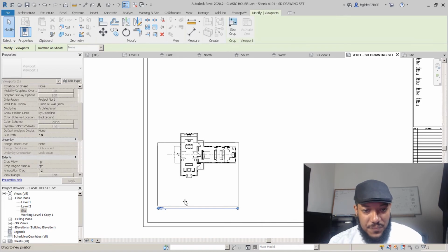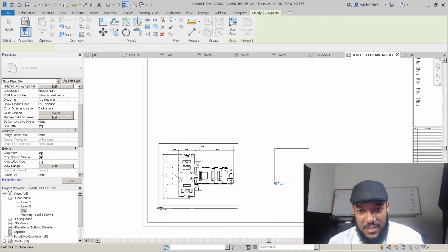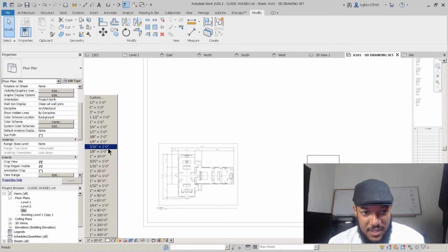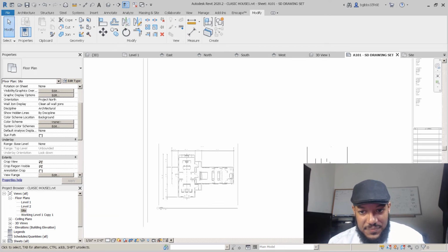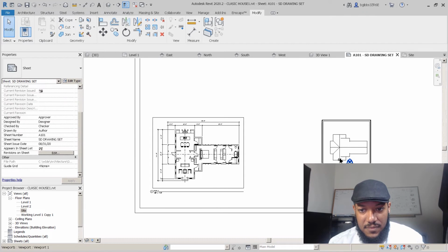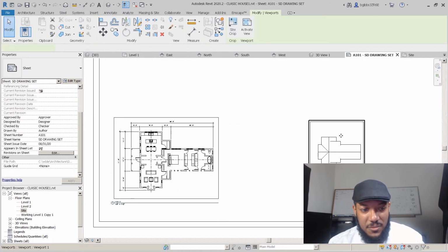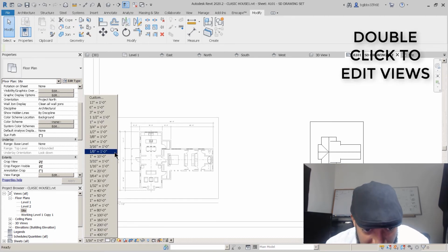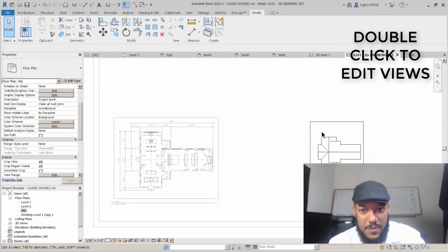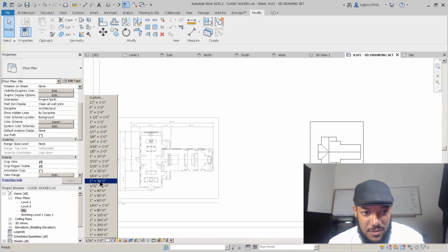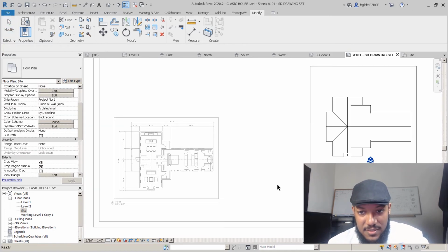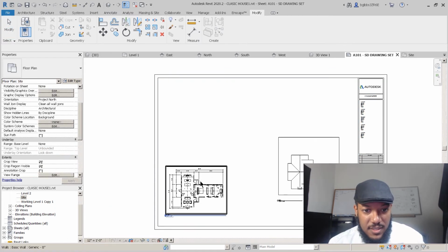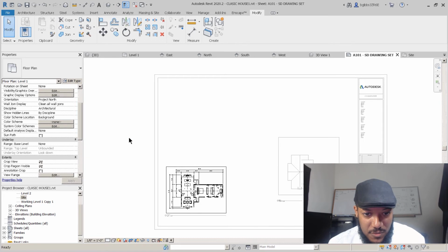Okay, so we have our plan here. Put our site plan here, and we probably want our site plan maybe 1 to 16. But for our sake, since we're not really showing too much, we can just make that 1/8 inch, sort of small. Maybe we'll put this to 1/4, or actually we make this 1/8 inch because it's sort of small. We'll make sure we see what we can fit on the page when we do this. Residential, you typically go to 1/4 if possible.